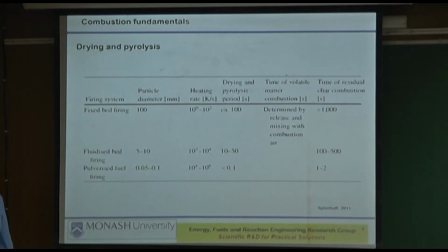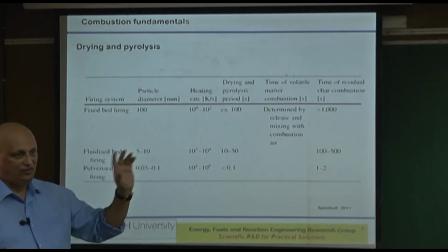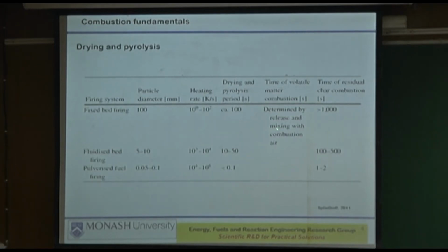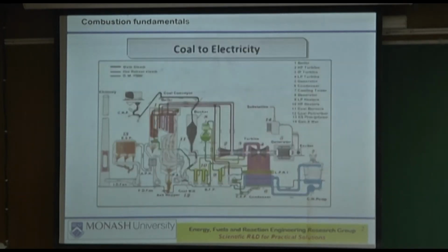If it is bituminous coal, it has a bit more volatile. Subbituminous, more. Lignite or brown coal, almost 50% of it is volatile. But volatile combustion is essentially fast, of the order of 1 or 2 seconds at most. Theoretically, between here and there, where you expect all the combustion to be completed, you are looking at only a couple of seconds at most.